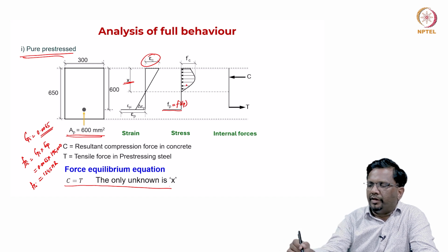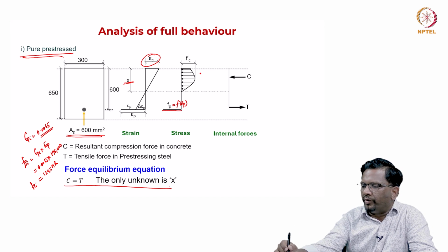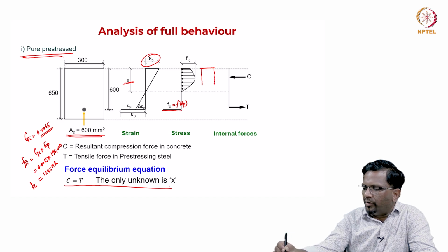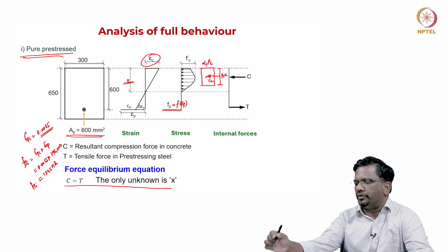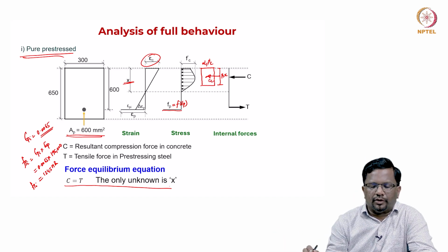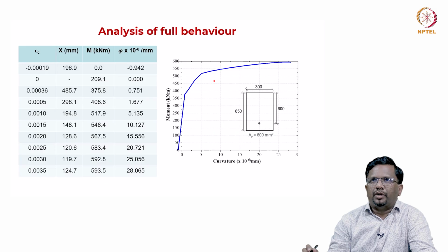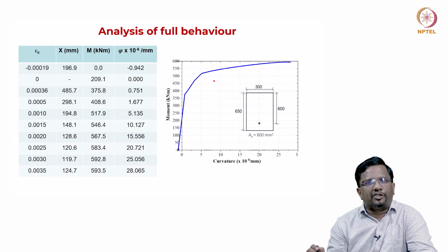Similarly, we are going to convert this stress block into an equivalent stress block like this: this is alpha 1 F prime c, this is beta 1 x, this is your Cc. Let's see how we do that, and we will explain the step-by-step procedure.